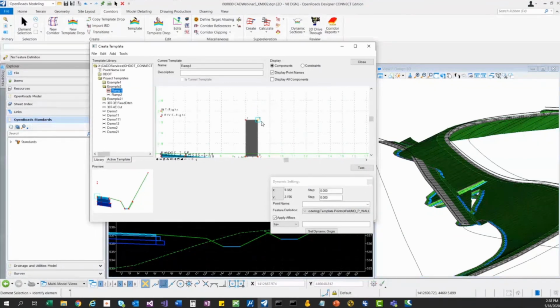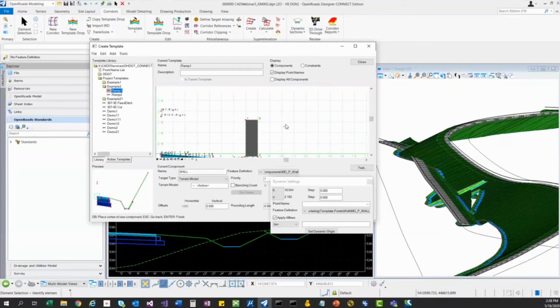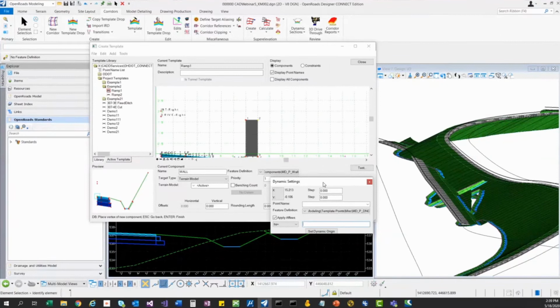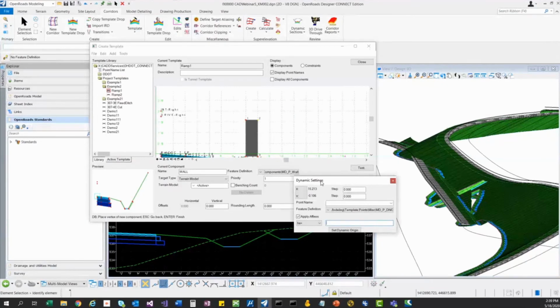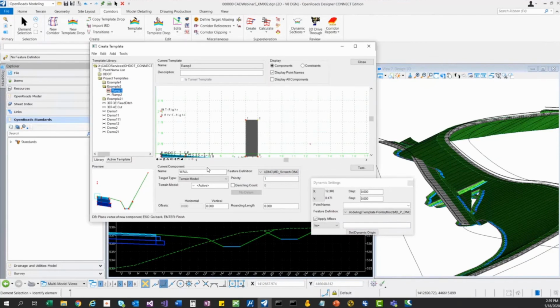So now, in order to get this slope, this grading to find this higher elevation ramp, I need a null point in here. So what I need to do is add an end condition here, and it's going to just be a null point. So if I go to my miscellaneous, I say do not construct point. What component doesn't matter since I'm not going to actually draw it in. So give it a DNC as a name.